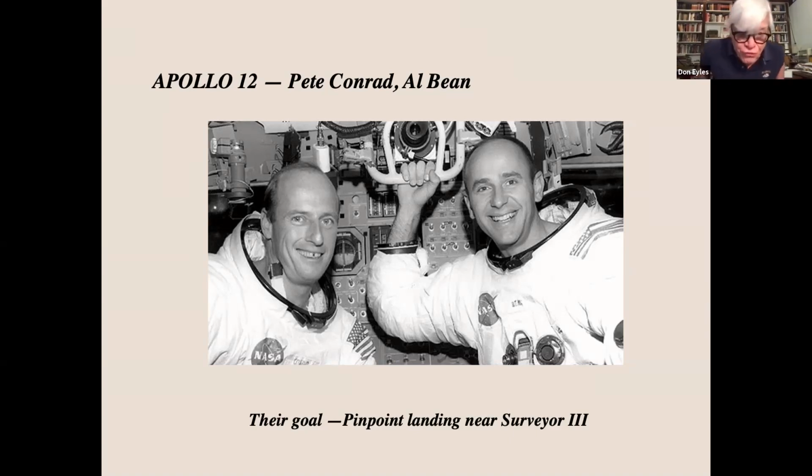The software implications of trying to make a pinpoint landing were the fact that there was no good way. The radar could measure the speed across the surface and correct that, and could measure altitude and correct that. But there was nothing on board except the human eye that could recognize a place and try to go land there. And for the human eye to pick it up, you had to be pretty much in the right spot at pitch over at the beginning of the visibility phase for them to be able to recognize where they were.